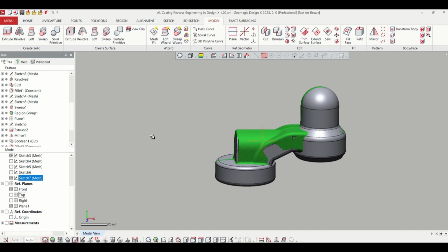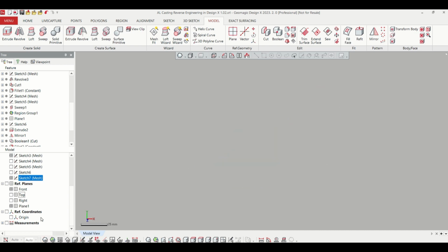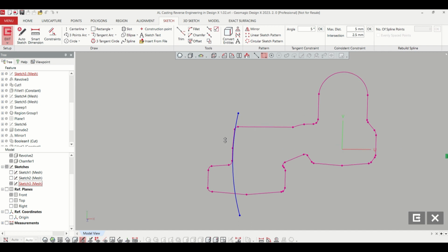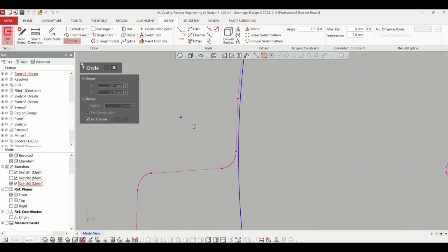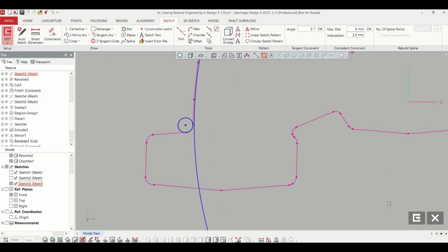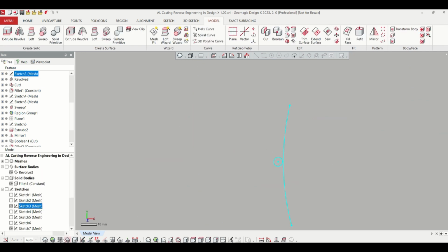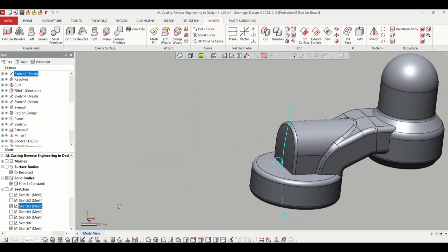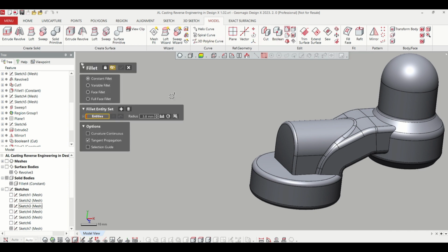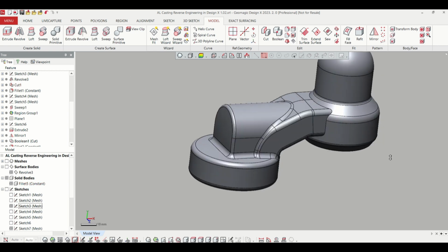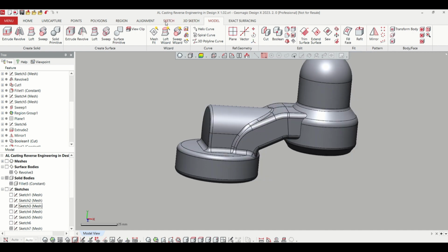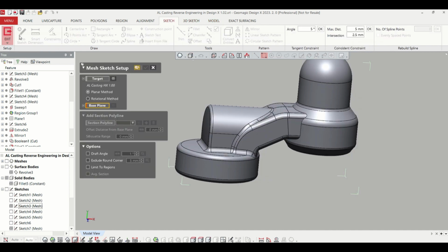And from a prior sketch, you can get a peek at what that fillet should be down here. Let's do a best fit on this arc, 2.8. Let's go with 3. We can always change it later easily if we don't like that result. So we'll do a fillet and 3. Looks nice.